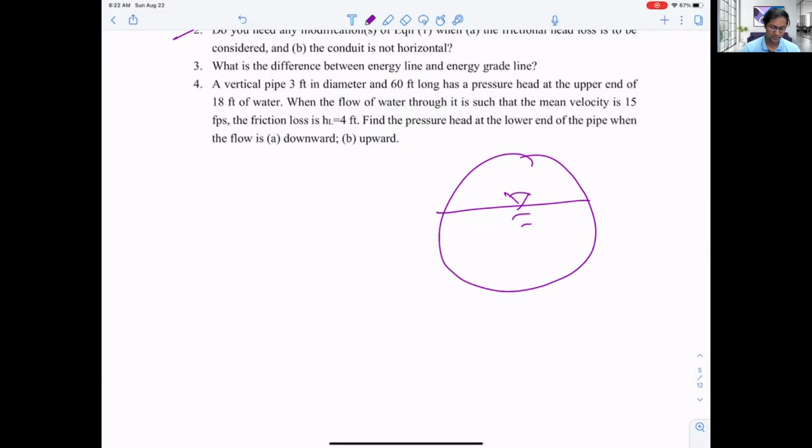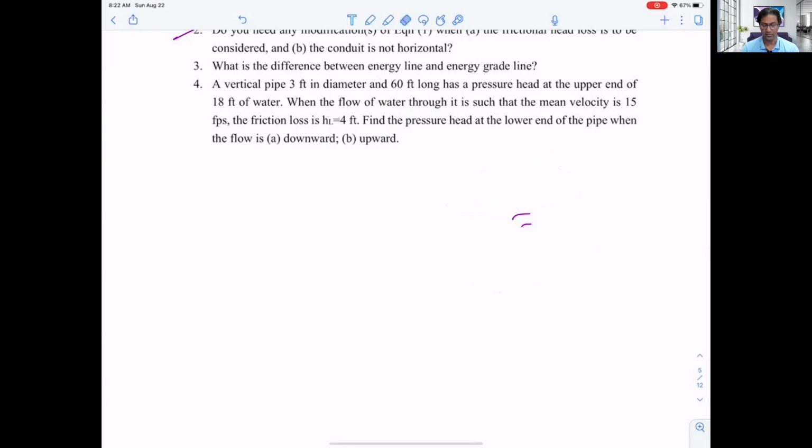It doesn't mean that always if we have flow through a pipe, it will be pipe flow. For a water distribution system, it will be pipe flow because the flow is pressurized. However, for a sewer network, we have a flow that is half full, so then it will be open channel flow. That's why we have to check the system, and we have different hydraulics, different calculations, different equations for dealing with all these conditions, open channel flow and pipe flow as well.